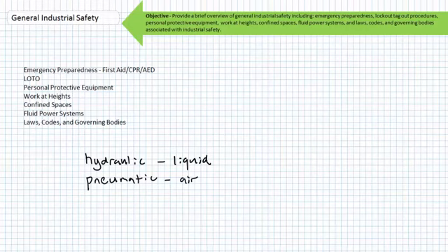Compressors in pneumatic systems can be unusually hot during the compression process and equally as cold when being discharged. The oil reservoir for a hydraulic system can be filled with hot oil, and heat exchanger devices can still be warm. Allow time between shutdown and maintenance for these components to cool. There are similarities between hydraulics and pneumatics, but there are also important differences. Do not think for a moment that by understanding one type of system, you are also an expert in the other.